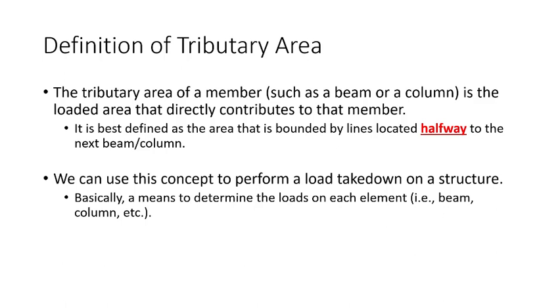Now, there are some instances where buildings will use two-way slabs. So the idea is that there really isn't a line of beams. You have a grid of columns, the slab sits on top of that, and the slab actually bends this way and this way. So it looks almost like a square trampoline that's bending down like that. We call that a two-way slab. We use two-way slabs whenever we're really interested in making the floor system shallow.